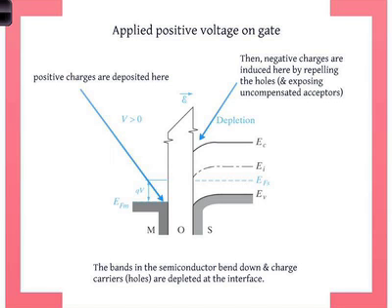Okay? If a small positive voltage is applied, then you have the cutoff regime, or the linear regime, if you are slightly above the threshold. But let's start with cutoff. Okay? So in this case, when you apply a small positive voltage, you get positive charges here, and the bands bend the opposite direction, so we're familiar with this. The Fermi level of the metal goes down, Fermi level of the semiconductor goes up, and the difference is the voltage. Here the bands bend down, this Fermi level has to be flat.